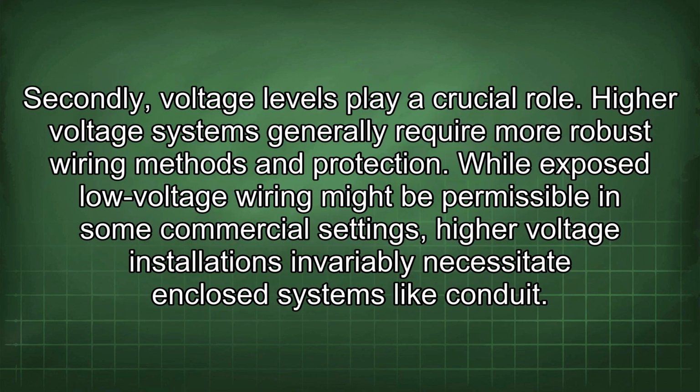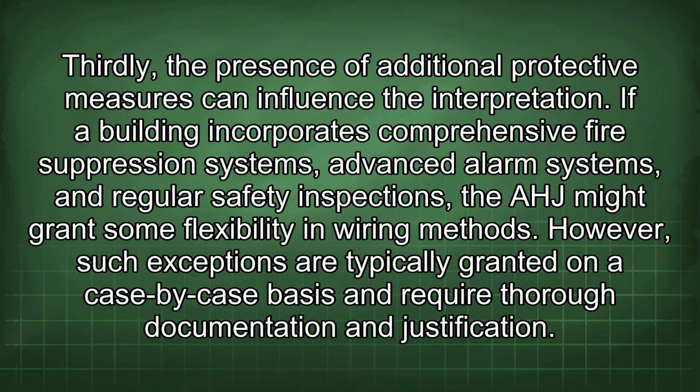Secondly, voltage levels play a crucial role. Higher voltage systems generally require more robust wiring methods and protection. While exposed low voltage wiring might be permissible in some commercial settings, higher voltage installations invariably necessitate enclosed systems like conduit.